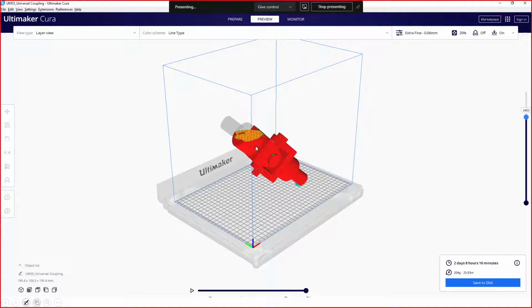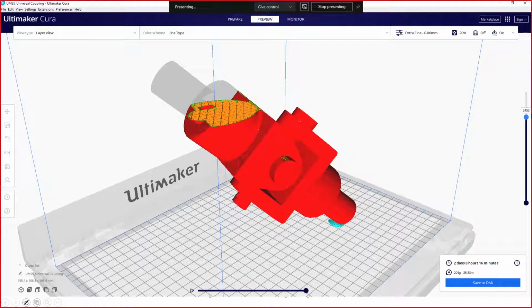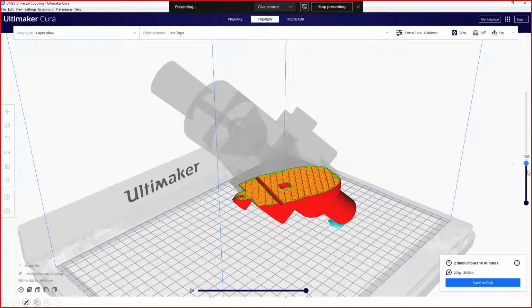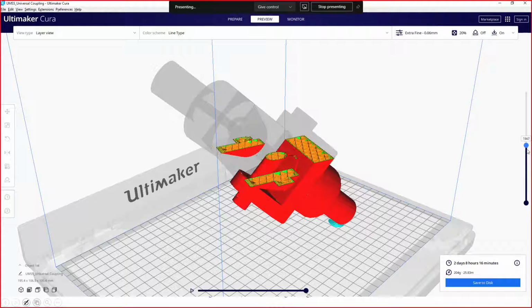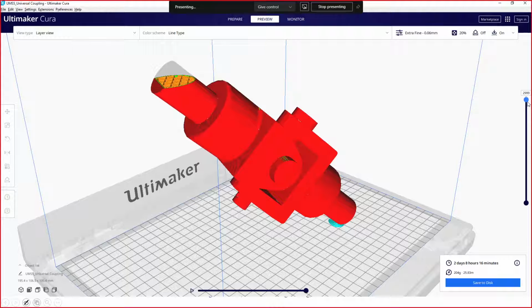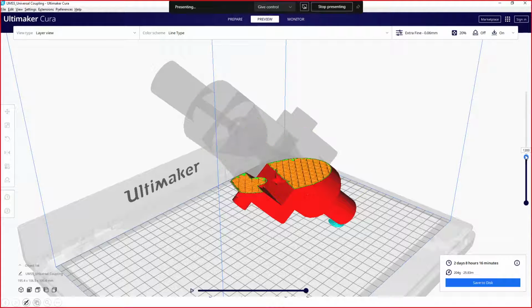So this is showing you how these layers are being printed. Here you can see the orientation of your component does not have any relation with the slicing. Actually, the slicing always takes place in the horizontal plane. In whatever orientation you are putting, your slice data will always be generated in the horizontal plane only. One horizontal plane over another horizontal plane, then another, and accordingly the data will be generated.